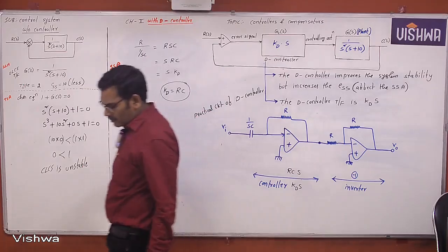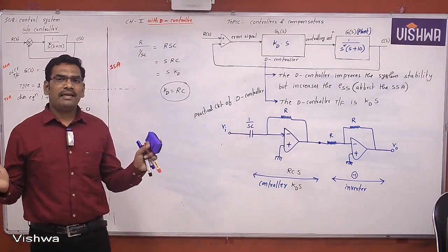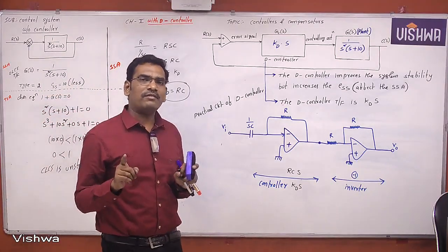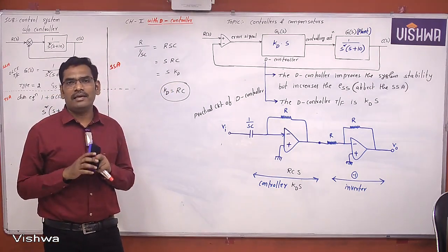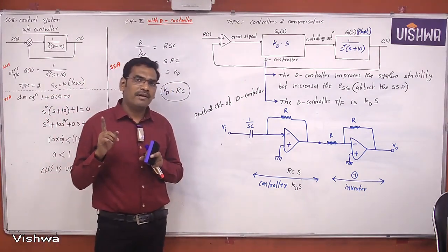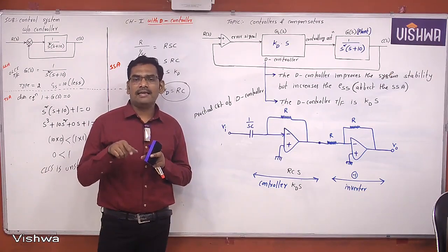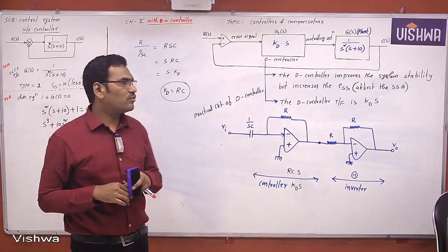Okay. Now students, what can we understand finally? Even we can take the P controller, I controller and D controller. One controller will do one good job and the same controller will affect another thing. If one improves the transient, another affects the steady state. If one improves the steady state, it affects the transient, right? Like that, this is the problem with the controllers we are facing.